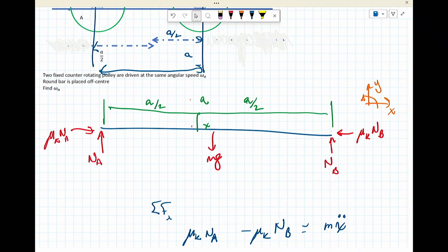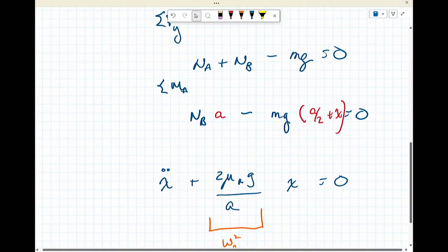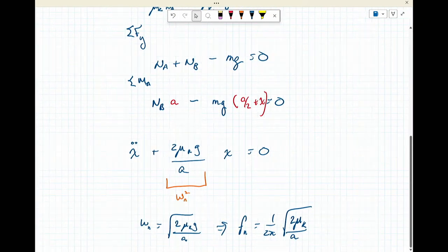But if you look at the figure there, I only have very few forces acting on this thing. I only have friction, I have normal forces, and I have the weight. Once you have all those terms in there, you can write an equation of motion, and I can do that in terms of any of the expressions here.